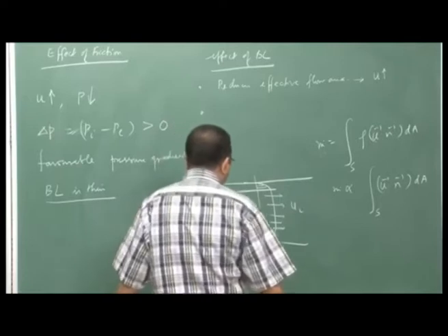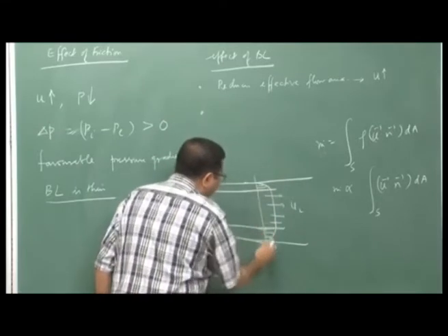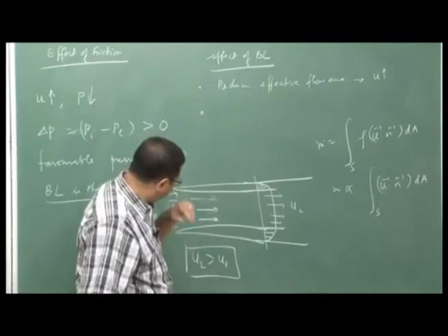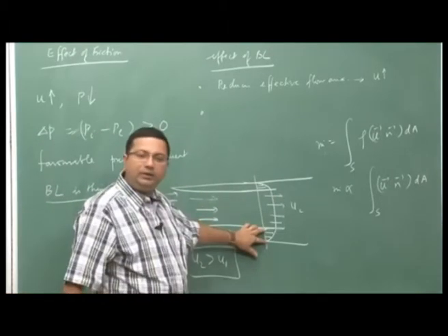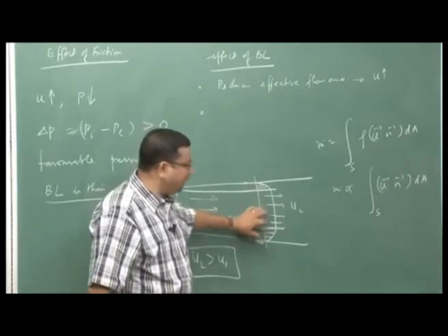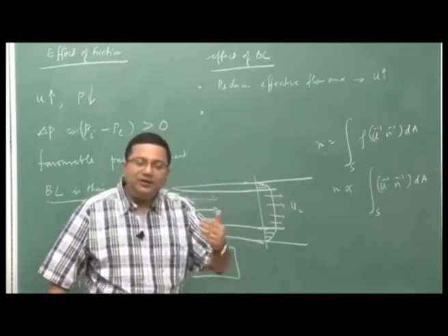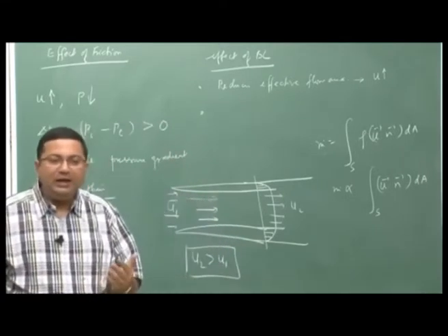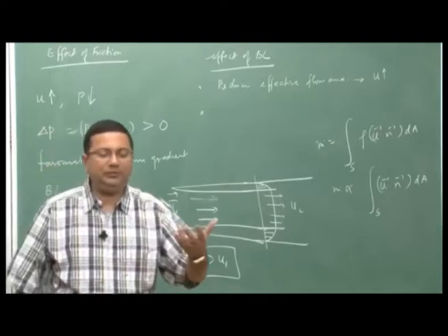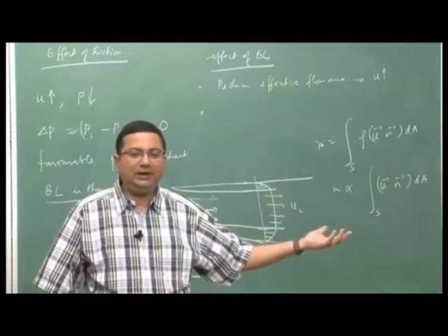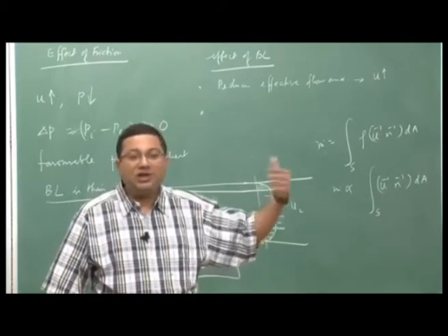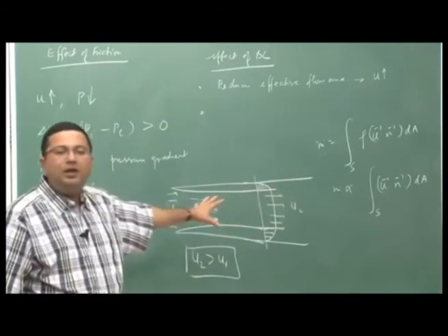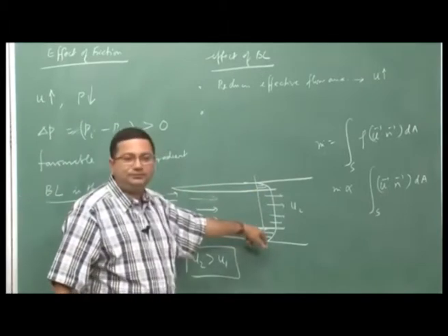Secondly, if I look at these two conditions, the flow is slowing down here, right. Because of that, there is a net deficit of the momentum, momentum goes down, right, and we have seen that the rate of change of momentum is the parameter that will dictate how much thrust we will produce. So, now the momentum is decreasing because of the slowing down of the flow here.